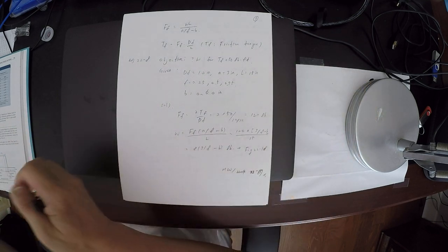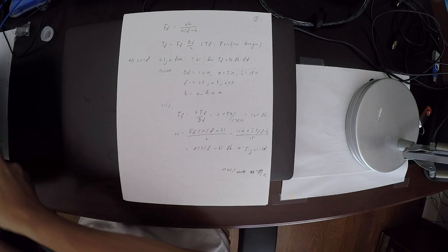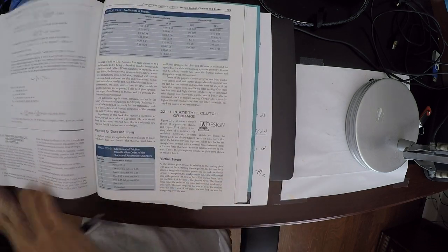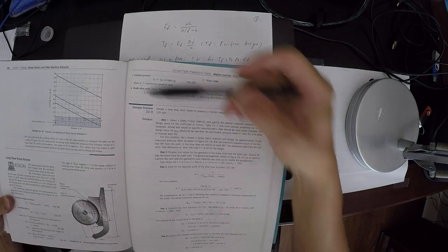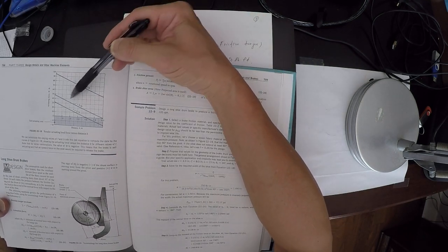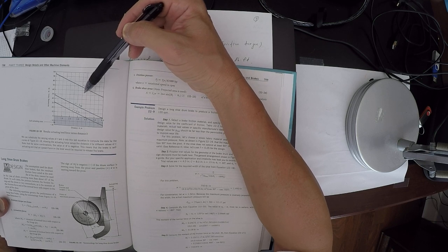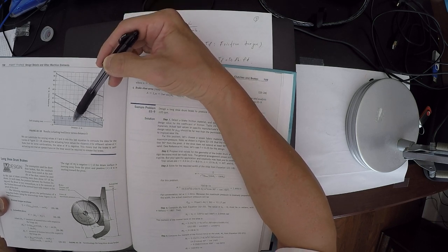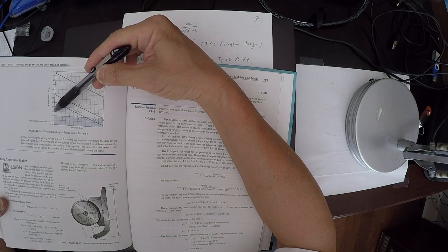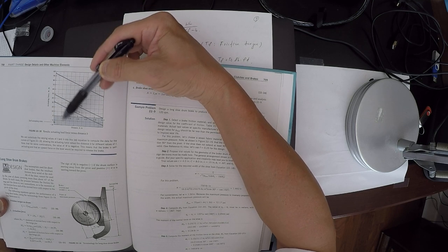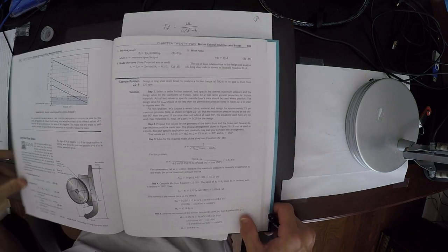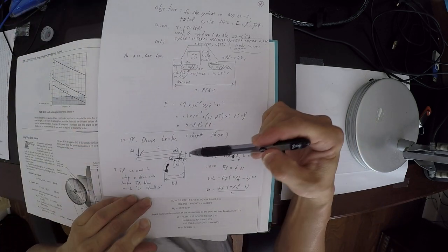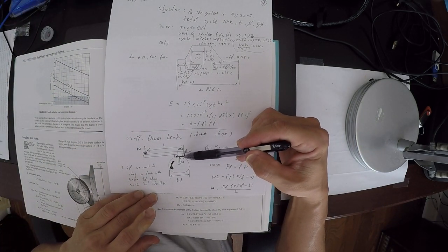So if we look at figure 22-18, depending on the friction, static friction, I believe, I'm sorry, dynamic friction, I believe, you actually will have to apply different force W depending on the distance B. So B is again the distance between the center of rotation to the brake pad contact point with the drum.